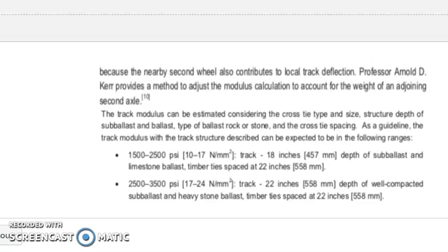It is packed between and below and around the ties. It is used to bear the load from the railroad ties, to facilitate drainage of water, and also to keep down vegetation that might interfere with the track structure. So that is the track bed of our track system.